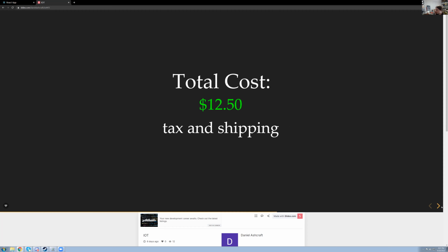The way I was going to get that price was essentially by doing injection molding and a soft body housing for it. That would be a soft body or a rigid body impact frame, and then an injection molded TPU or similar soft body elastomer to protect against environmentals. But in this particular case, all the power is being provided by a 5-volt external power supply, so there's always that cost as well.